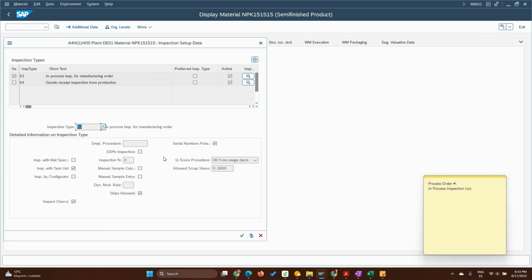So sometimes the pH, for example, during a process is not necessarily the same pH as in the final product, right? Because you need to reach a pH before loading one raw material, which is pH sensitive, for example. So if the pH is not appropriate, then you cannot load that raw material. And after loading that raw material, the chemical reactions will end up with another pH in the product.